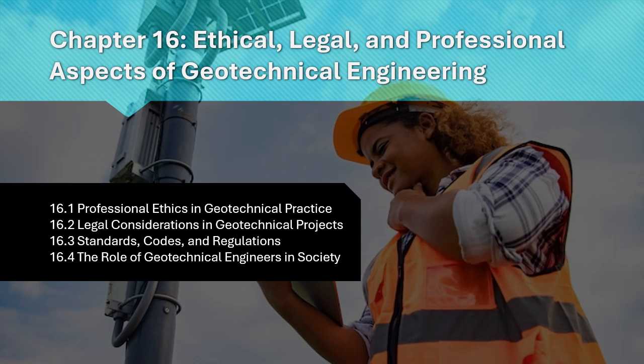OSHA standards. Occupational Safety and Health Administration in the U.S. OSHA regulations govern construction site safety, including the safe design and execution of geotechnical fieldwork. The regulations address issues such as trenching, excavation, and the safe operation of drilling equipment.